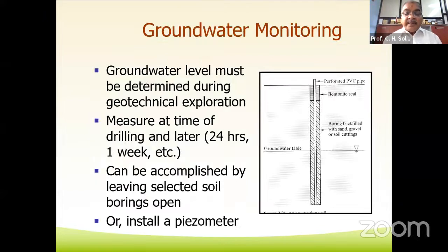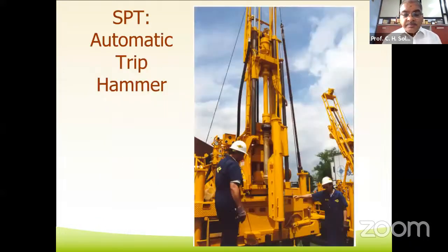Groundwater monitoring is required. Groundwater level must be determined during the geotechnical exploration. Measure at the time of drilling and later after 24 hours. This can be accomplished by leaving selected soil borings open or installing a piezometer for measurement of the groundwater table. This is showing you the SPT automatic trip hammer.